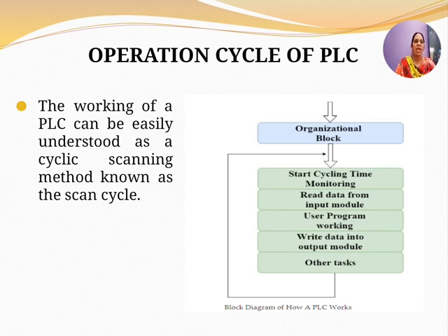So the PLC can be operated on the input side. You can operate the PLC by analog or digital input devices. Field devices such as level switches, pressure switches, flow meters, as I showed you in the block diagram, are connected to the system input. The PLCs can drive analog or digital output devices. Motors, solenoid valves and other electronic devices are connected to the output devices.